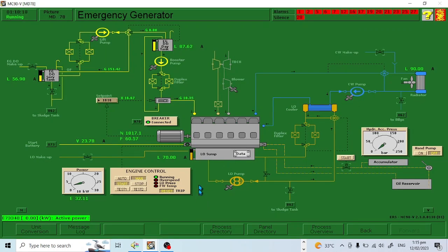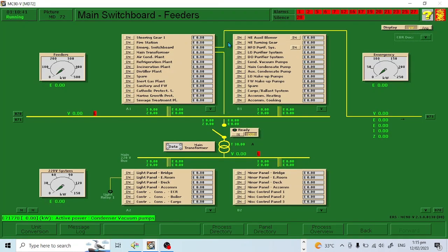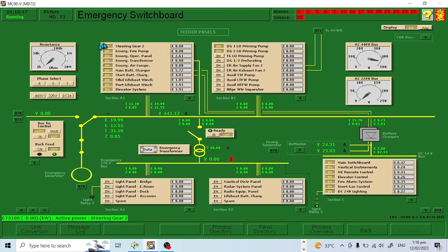You go inside the generator, you check the lube oil level, the power, the sounds, the leaking, and you are also going to include the idea of checking that these breakers are on. For example, this one is not switched on. You can report to your senior engineer that one of our breakers tripped off, or one of our breakers is not in a closed position.